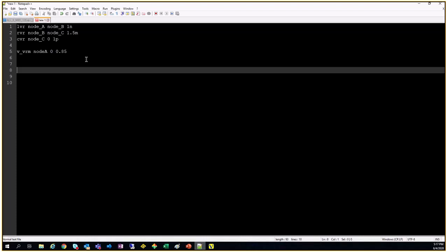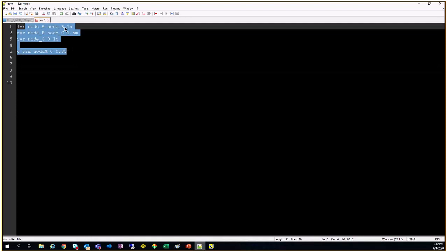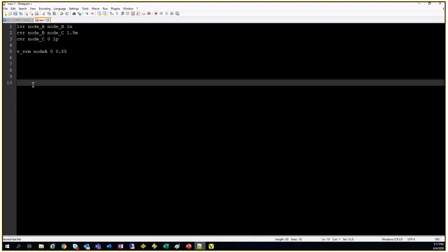You're going to hook it up to different nodes. So instead of every time hooking it up like this, say 1 nano, 1.5, 1 milli here, then again repeating it between node A and node D, the same RLC network, you want to hook it up again and again. You will say between these two nodes, hook up this RLC circuit. You want to do it like that, okay?